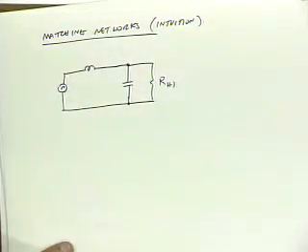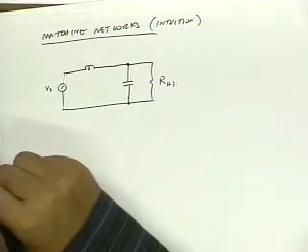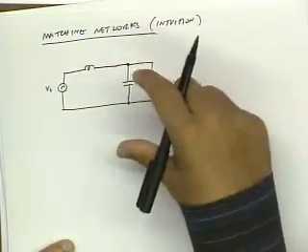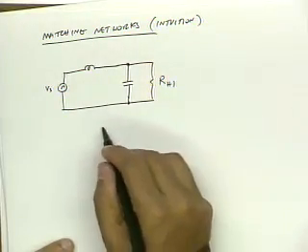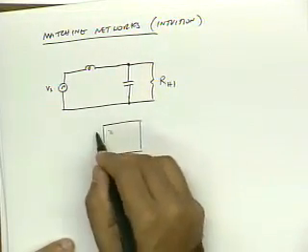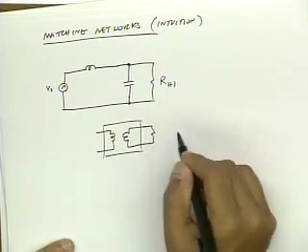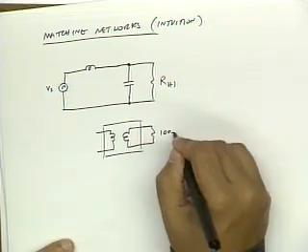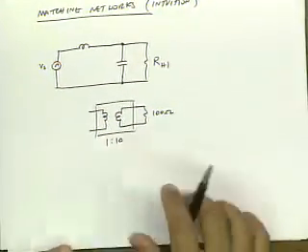this L matching network is going to transform this to R low. So what I'd like to do is take this voltage source and somehow boost the voltage that drives this RL. In other words, if I go back to my picture of a transformer, let's say this is 100 ohms, okay? And let's say this has a 1 to 10 turns ratio.